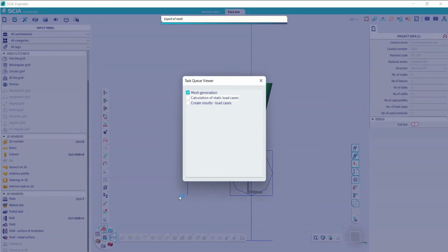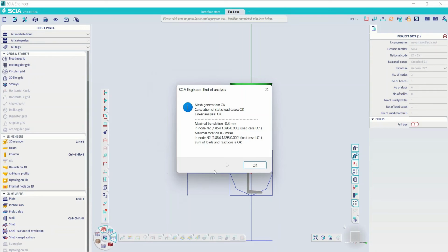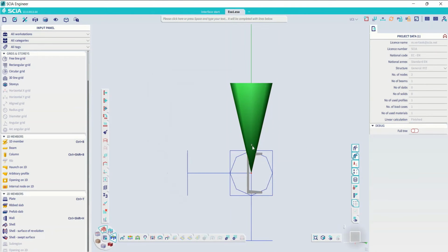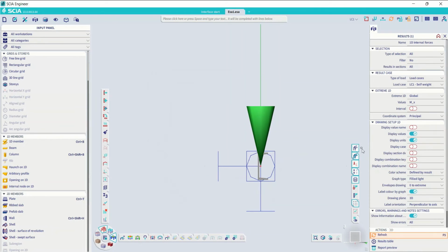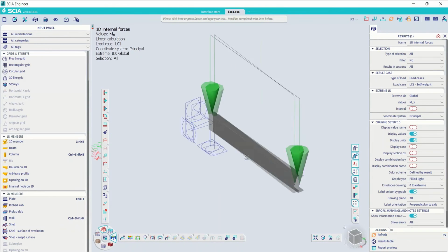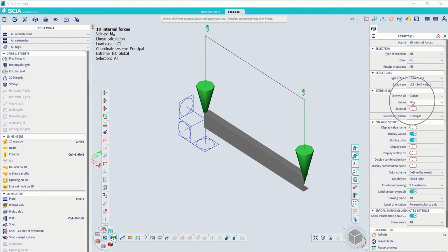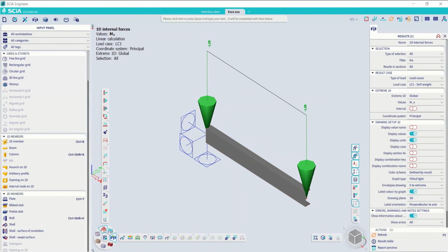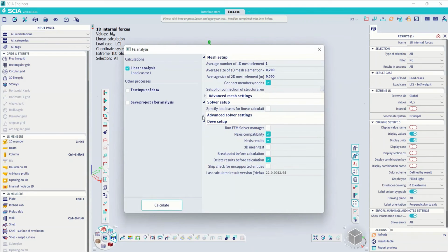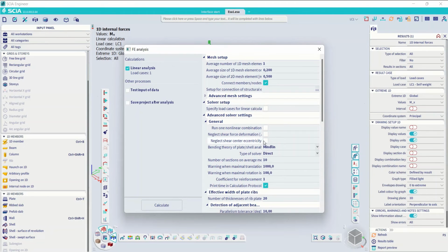So right now, I enabled this option, which means that the load is taken into account in the shear center, while it is actually visualized in the center of gravity. And so if I look at the torsional bending moments, there is no torsion in this element currently, because of this option that I enabled. If this would be a new project, then this option would be disabled.